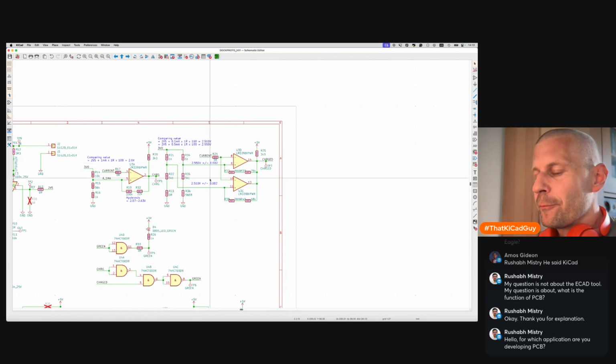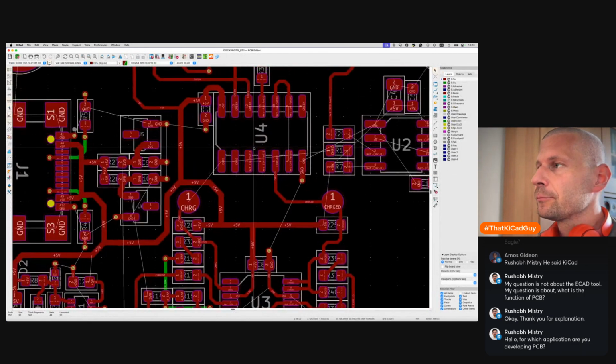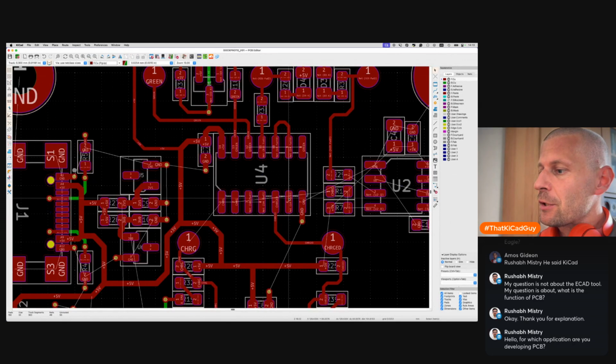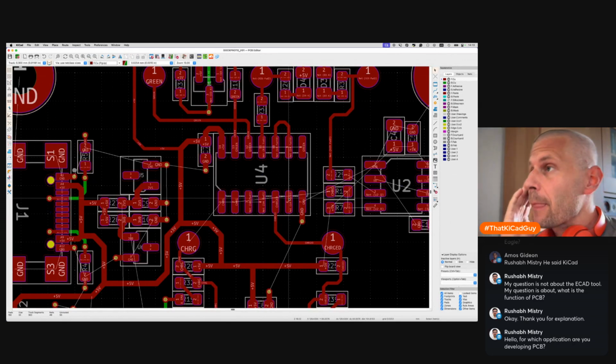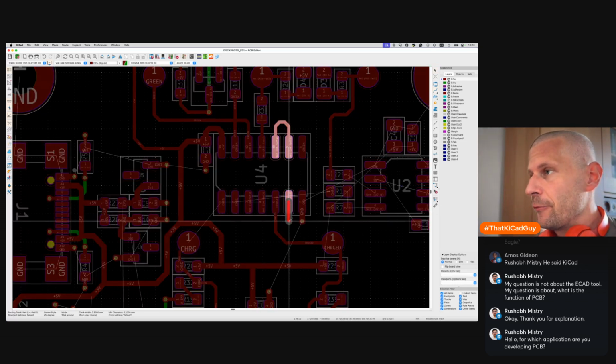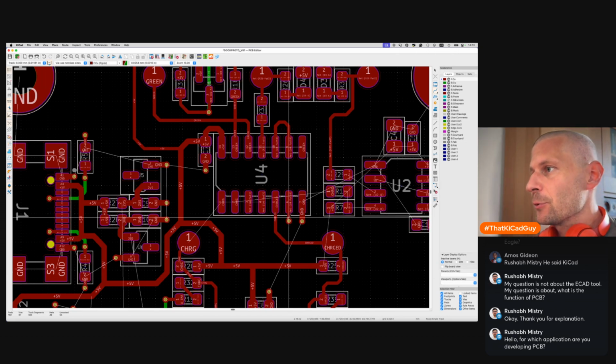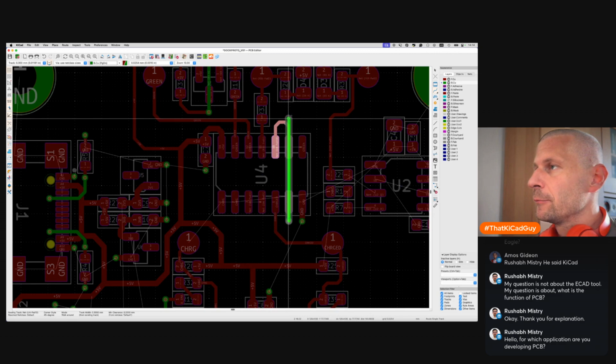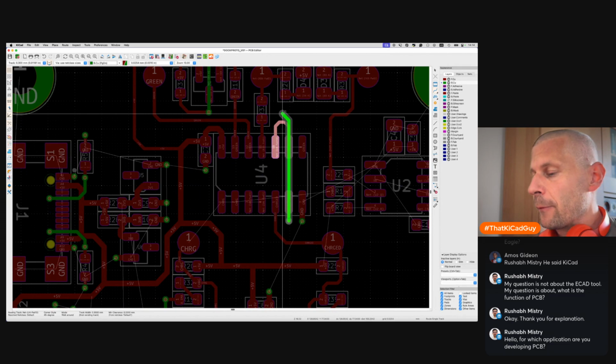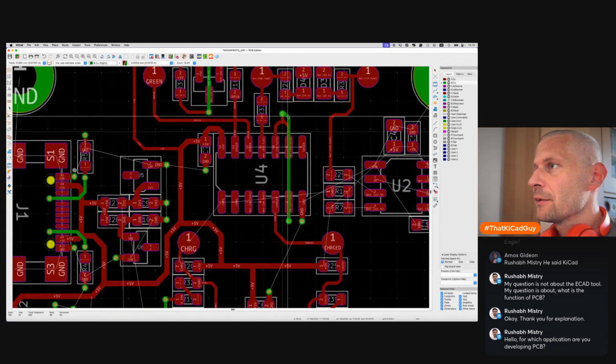What I might have to do is change the logical circuits, so the logic gates. So this is why I will keep the possibility to change the circuitry by cutting the small short tracks near the pads. So here I will use the via and connect it like this. It's not nice, but it's functional.